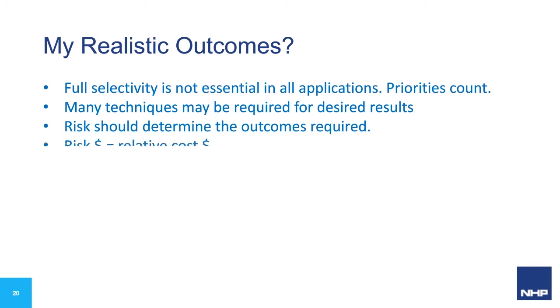The risk factor should have some bearing on the level of selectivity chosen. However, understand risk and investment in the outcome both equate to the possibility of outgoing dollars. And don't forget the reliability and the design of the backup system, and this needs to be incorporated into the selectivity design to ensure proper operation in the event of a short circuit fault.